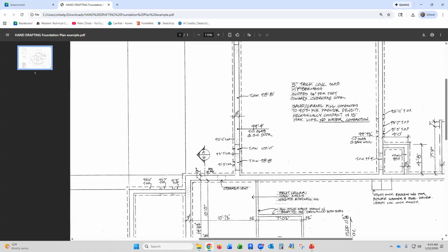So it's very important that you slope that garage to get all the water and snow falling off your car to go out the overhead door. So the long-winded way of saying all that is that the reason that slab is sloping is to get it drained out the door. Now, I don't want to stop the slab where the wall is. I want to have the wall drop down where the doors are so that slab can go over, because otherwise it would see that joint between the slab and the wall.